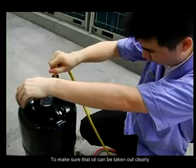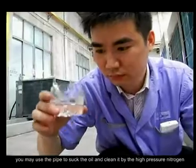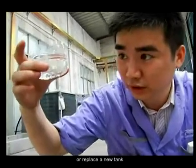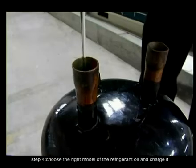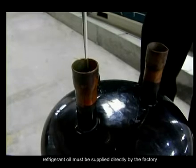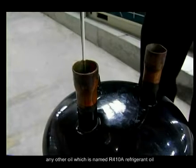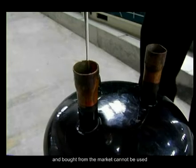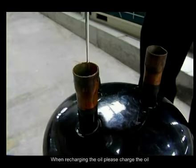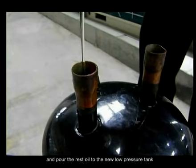To make sure the oil can be taken out completely, you may use a pipe to suck the oil and clean it with high pressure nitrogen, or replace with a new tank. Step 4. Choose the right model of refrigerant oil and charge it. Refrigerant oil must be supplied directly by the factory. Any other oil named R410A refrigerant oil bought from the market cannot be used. When recharging, charge the oil according to the new compressor's required volume and pour the rest of the oil into the new low pressure tank.